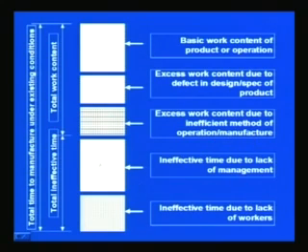While ineffective time is also added to the total work content to find out the total time required to carry out the given job. This ineffective time may be due to the lack of initiatives from the management, or ineffective time can also be caused by the lack of workers' contribution. When they do not do things seriously which are expected to be done by them, that leads to the ineffective time by the workers.